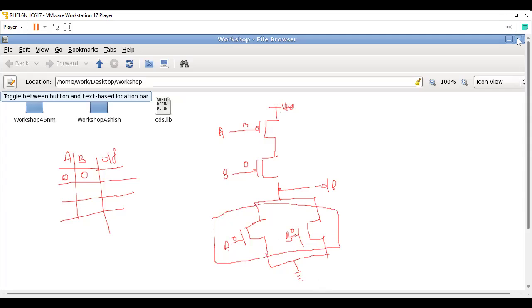Getting the point? Because when you have any circuit like this, these are on, so these behave as short circuit. So how will this circuit appear? This is VDD. This PMOS is short circuit. This PMOS is short circuit. Then again the PMOS is short circuit. Then there you have output. Then below that you have two open circuits.